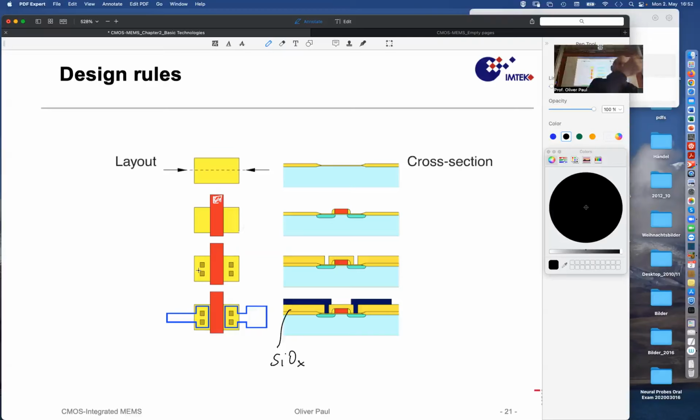A slit is a 1D object, whereas a hole is a kind of a zero-dimensional structure. Roughly speaking, the etch conditions in a slit object are going to be different than those in a structure that is limited in 2 dimensions. There will be different load factors, and you would like to have this etching progress at the same speed everywhere.